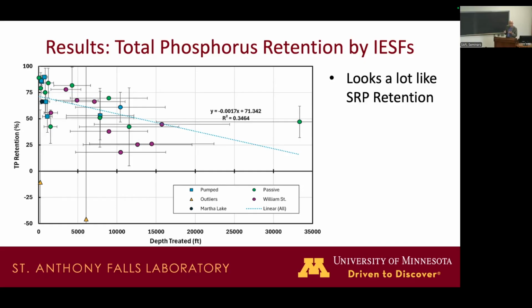And so when you're capturing these things, when you're capturing particulates, eventually, if you leave it there long enough, you'll be releasing phosphate. So that's something that comes with the territory. You're capturing stuff, and the capturing stuff degrades, it releases something. So even to remove particulate phosphorus, a sand filter cannot last forever. But anyway, this is a figure that can be used.